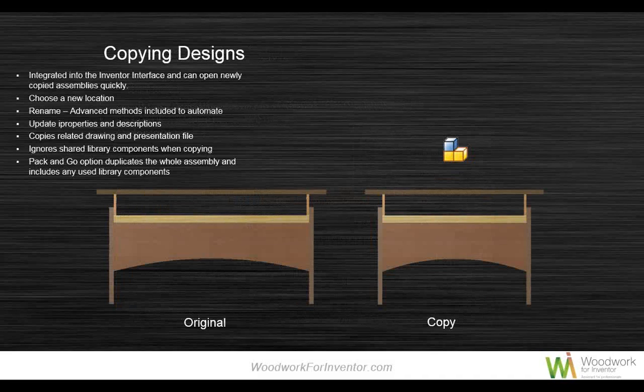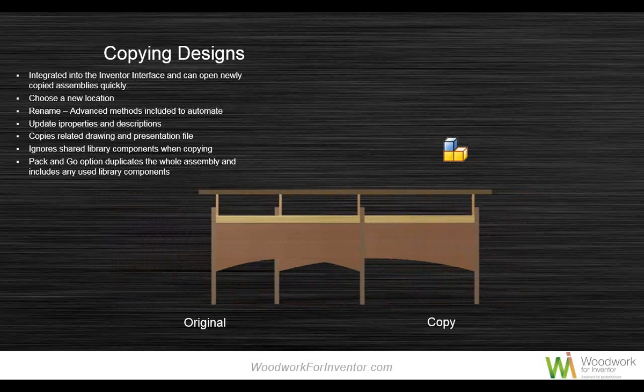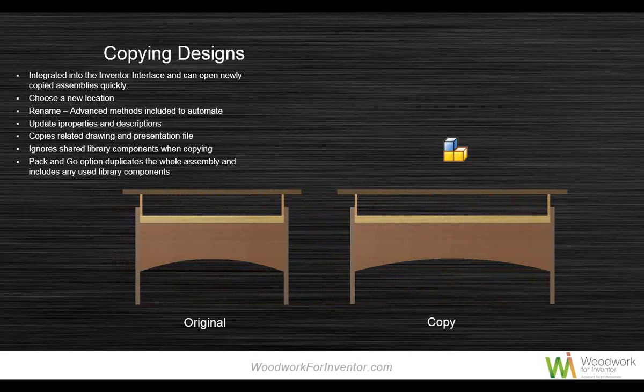So another challenge customers have moving to 3D tends to be that if they move from AutoCAD, they're used to managing a single file. It's usually a single DWG file. If you're a competent user, you might have gone down the external reference way of working, where you have a file linked to a top file, and that concept is primarily how Inventor works. It has an assembly file, and then it has multiple parts. So you need a tool that will allow you to copy that design within the graphics window, and then change that into the next variant. Otherwise, if I was to change the component in one assembly, it would automatically update the component in the opposite assembly. So we just want to be able to basically pick and choose what size of drawer we require for our particular cabinet, as an example.